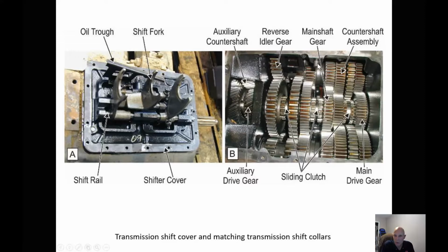The other thing to pay attention to is this little pin that's here. This is the actuating pin for our high-low range into our slave valve that you can't see off to the side. A lot of people drop these covers on, and this little pin breaks off. The easiest way to prevent that is to take our slave valve off first and put it back together last, once our cover's on, so that we don't break it.